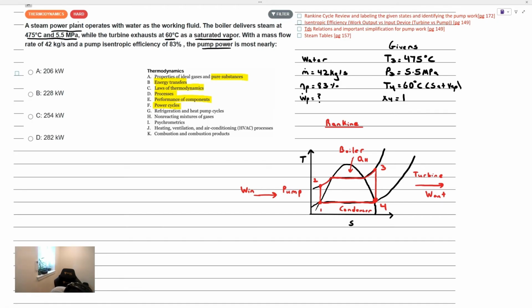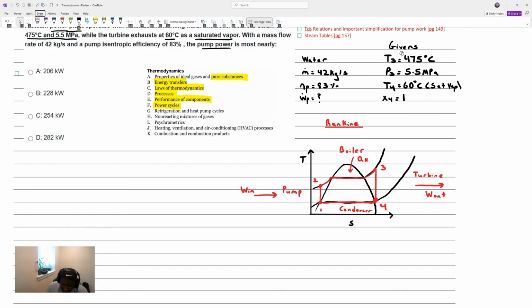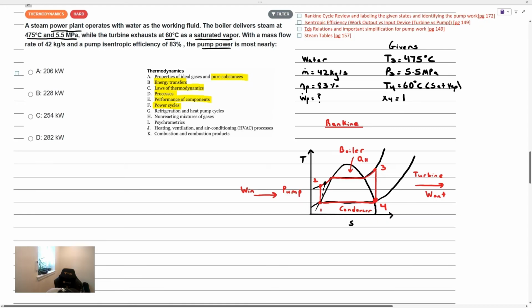Now, you can see that I drew all vertical lines, but this would represent the ideal Rankine cycle. The non-ideal Rankine cycle would actually have a kind of slope here because we would increase the entropy, right? So this would be the 2 actual, the actual state associated with 2. And for state point 3, which is an expansion device, we would actually slope to the right here. This would be the non-ideal Rankine cycle, before we drew the ideal Rankine cycle. To go from 1 to 2A, or to go from 3 to 4A, we essentially use the idea